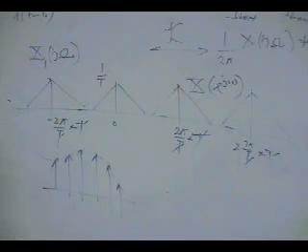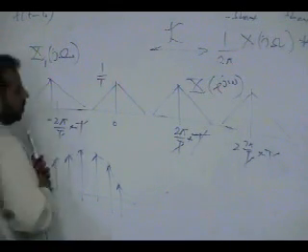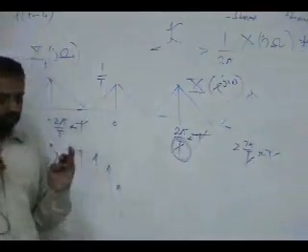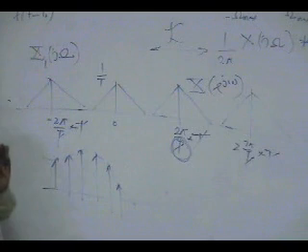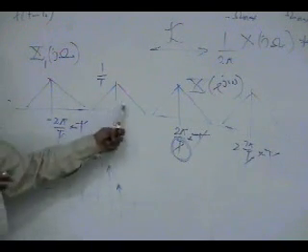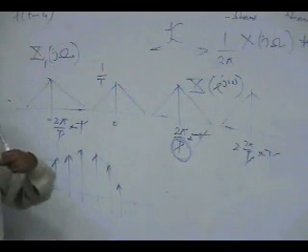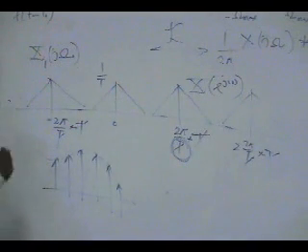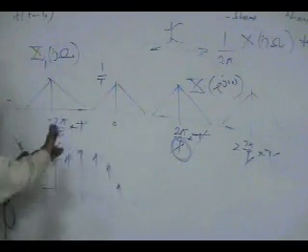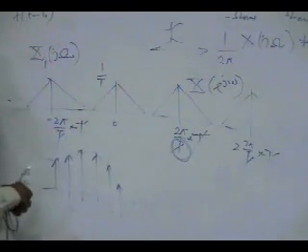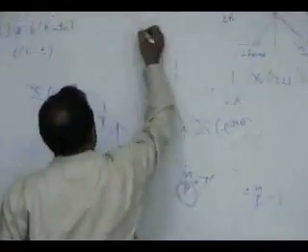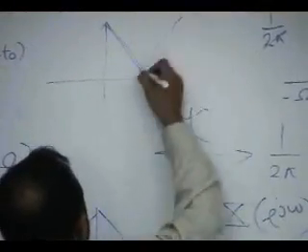But the important point here is that you need to make sure that you sample fast enough. So T should be small enough that 2π by T is far enough, so that you get copies which are not overlapping. You make sure that you are sampling fast enough so that 2π by T is far enough that you don't get overlap. So if I draw this neatly, all we are saying here is that this should not happen.